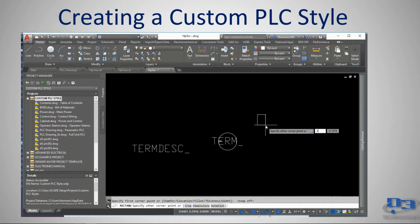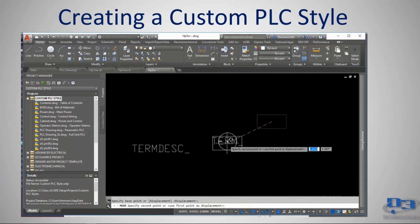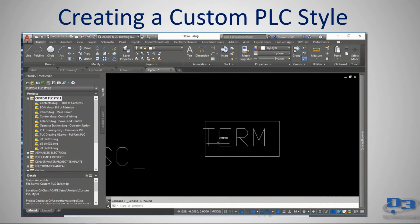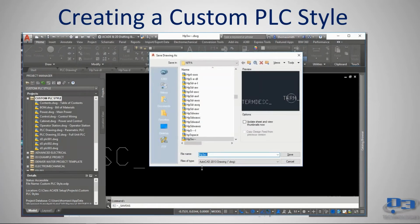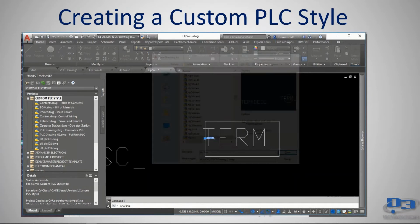So again, I'm just drawing my geometry, and this one's pretty simple. This one was just a terminal connection point wire left. So I am just going to simply switch out the circle for the rectangle, move the wire connection point, and this one is complete. All right, again, save as and NFPA library or whatever library you happen to be using at that time, and then changing the name of the style to reflect your style number.